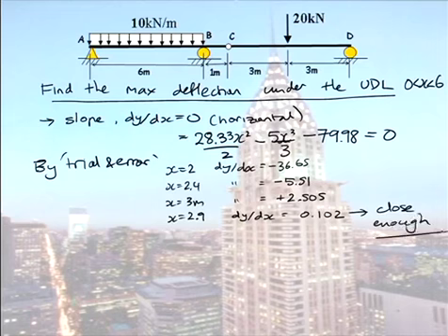When you actually look at deflection, if again I draw the deflected shape in here, well, I've just scribbled a really fat red line there. But as you can see, near the maximum, the slope is very flat. So even if you're slightly off in your location, you're going to get a very close value of your deflection.